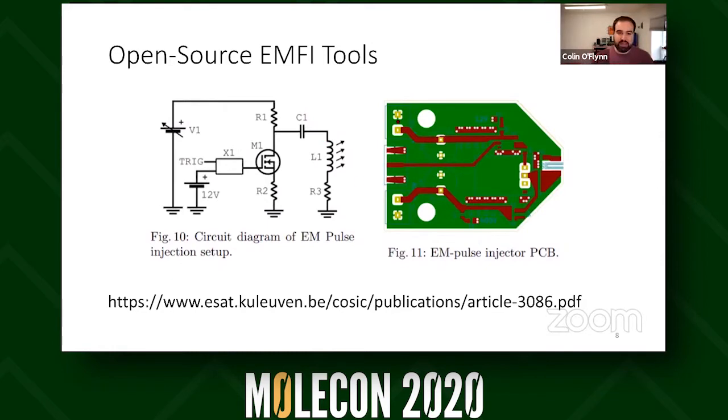There are other designs you see that don't have this capacitor here and put a switch at the bottom side. The problem here is you always have the high voltage on that probe that you're touching. So if you have your device, you don't want this to be at high voltage all the time, which some designs will do. And it's obviously not great if you're going to be handling it a fair amount. So it does work though, if you have the safety mechanisms in place. The first open source EMFI tool, BadFET, used this method, which is slightly more dangerous, but you had a lot more flexibility with voltages, pulse shape and stuff like that.